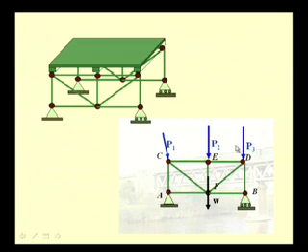One thing that we observe is that all these external loads are applied to the joints of the truss only, and the truss consists of many straight elements connected at their extremities. For a better analysis, we may also include the weight of the truss for better prediction of the internal forces.